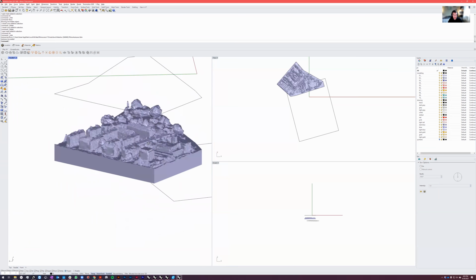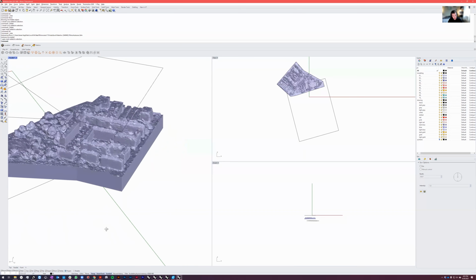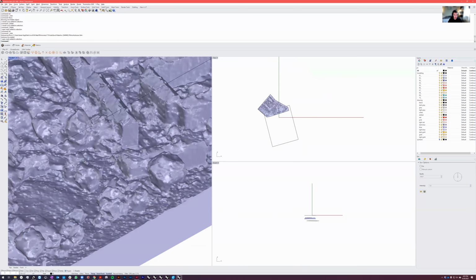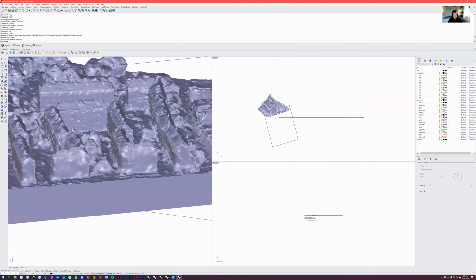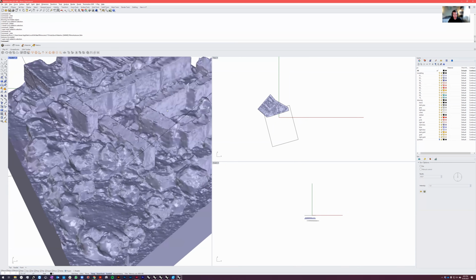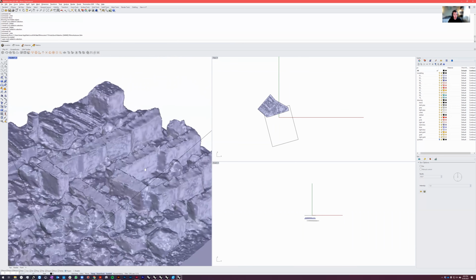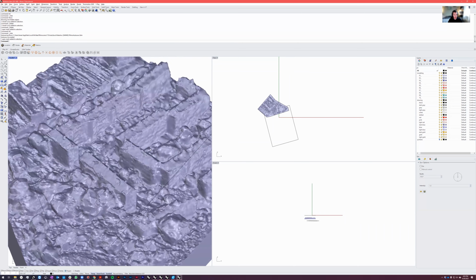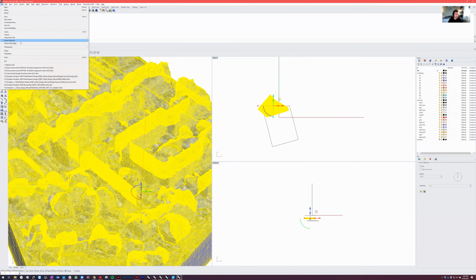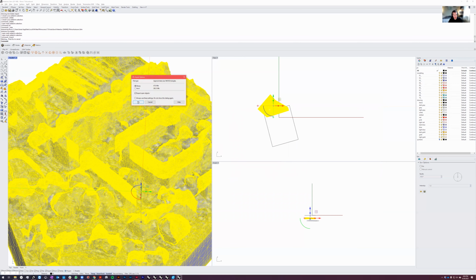So now I'm going to take this block and select it. You can see now it's come through as a decent mesh. It's okay. Probably could do with a little bit of smoothing. I think you could remesh this if you really wanted. It takes a little longer, and that could be a smart thing to do if you wanted this to be a little bit nicer. But for now, I'm just going to export selected. I'm going to save it in my 3D print folder as not Waterloo Station. And just press yes. Okay, I'm going to save this as a binary.